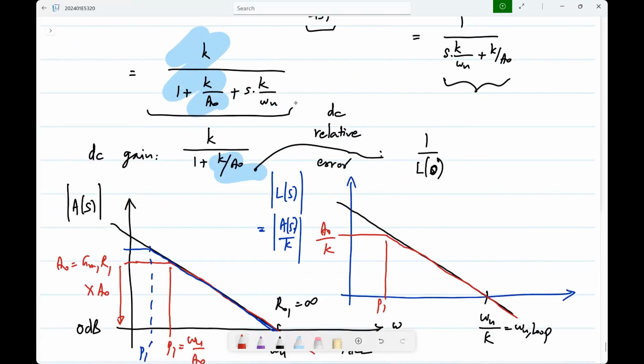Okay. So similarly, if you have a different resistance value, but the same capacitance value, only the pole changes. The unity loop gain frequency doesn't change. So what does this mean? If you apply a step, that transient is because of the capacitor, right? So that by and large remains the same. You are getting that exponential, it remains the same. Where the exponential settles to, that's what is changed by this resistor.